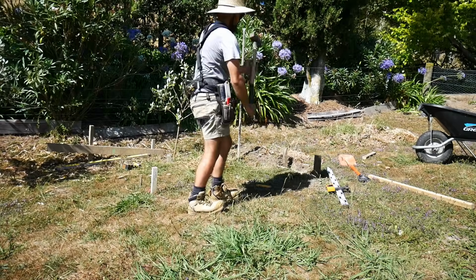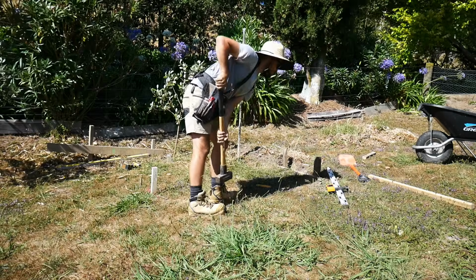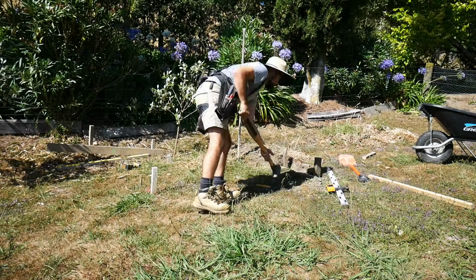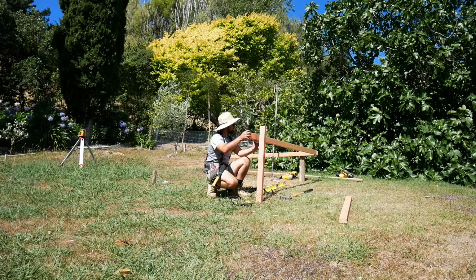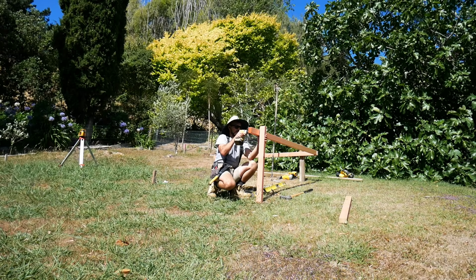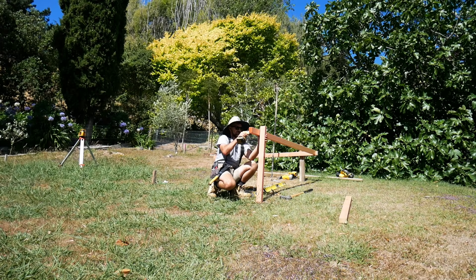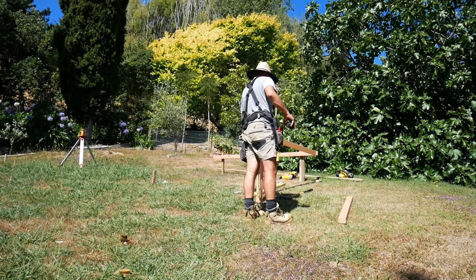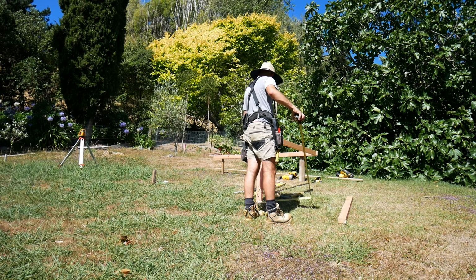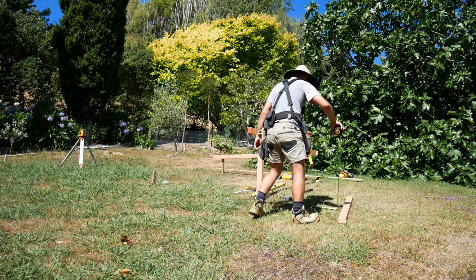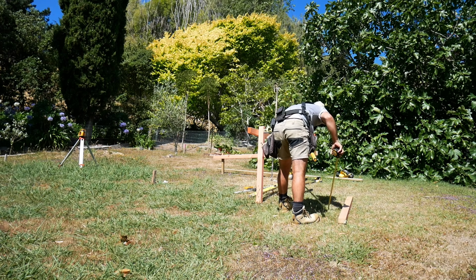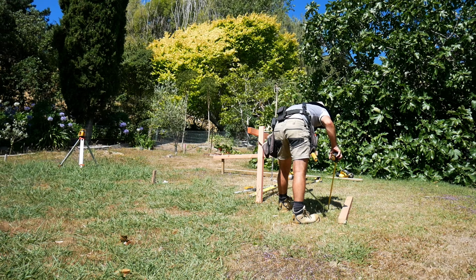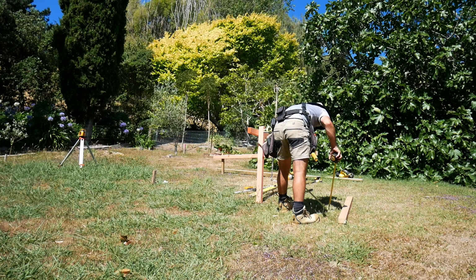These lower ones give you an indication of how much the back corner needs to be excavated. As I get higher out of the ground, my profiles need braces to stay rigid, and for the right angle braces to work effectively, they need to be no more than 45 degrees. The easy way to work this out is to measure the height above ground that the brace will attach to the upright, and that is how far out the brace needs to attach to the ground, also known as a 1-to-1.